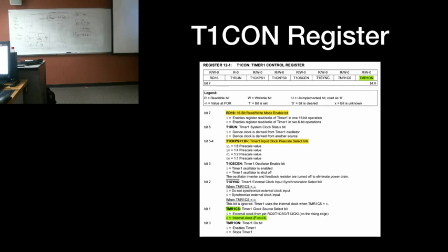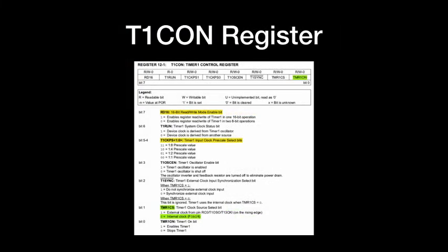This guy here, I want you to look at RD16. This is the enabled register read-write timer in 16-bit operations. This is what I consider an intermediate skill. So we will not be dealing with this right now. This does not make the circuit 8 versus 16-bit counter. It does not do that. This is nothing more than a 16-bit instruction cycle to it or an 8-bit instruction cycle to it. So don't even worry about that circuit.